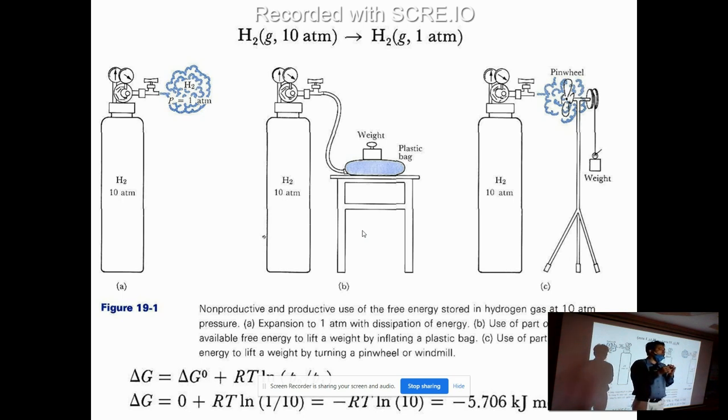More often people will talk about only the concentration gradients. Wrong. It's the chemical potential. It's the chemical potential of the species, the molecules, that is driving them to go there because the energy is more. As I said, in the case of iron, because it has come from the highest temperatures, it wants to lose the energy in order to become stable.